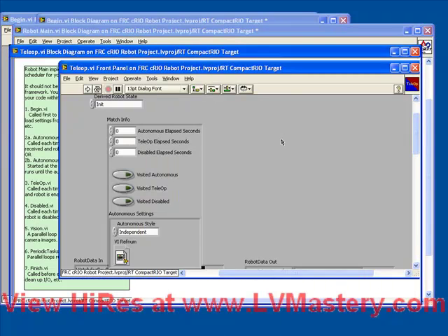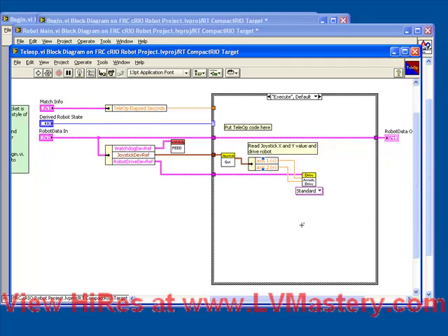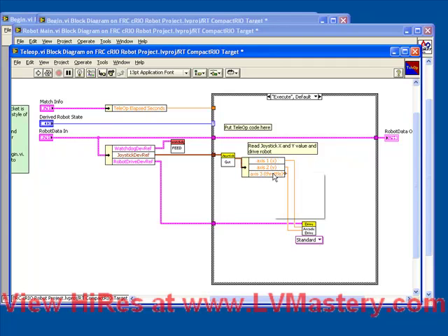Well, let's first edit our Tele-Op.vi to extract the information we need. We're not going to get rid of the arcade drive. We're just going to move it down a little bit. So we're going to read from a third axis. Let's choose axis 5. And we're going to read from the buttons. Basically, what we're going to do is treat button 1 as the manual override button for the mechanical lifter, and axis 5 as the speed command.